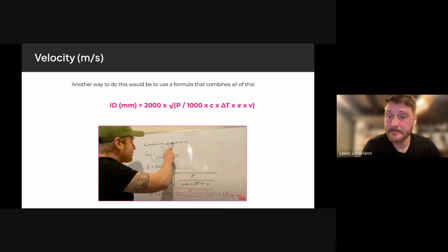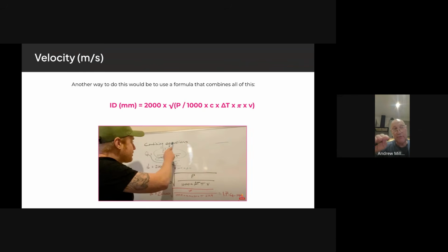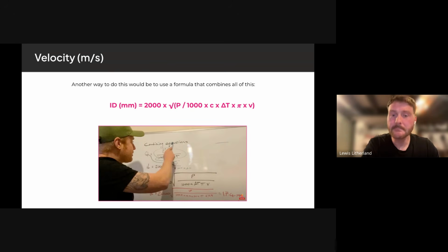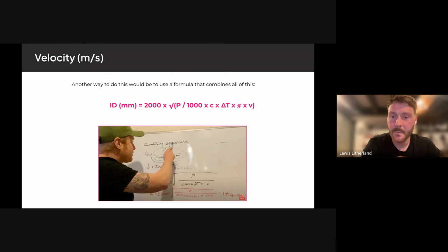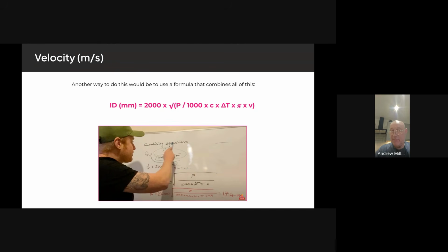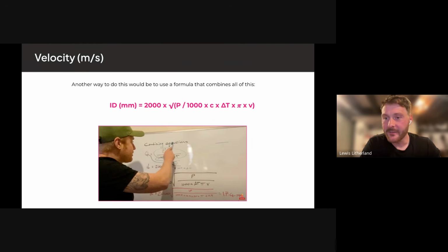I use this formula all the time. I don't do the process you've taught. I just look up the power needed for a circuit, put it through that formula, look at the diameter it gives me, and if my pipe's near enough, it's near enough. So it's a really quick, easy way of doing it. But I've always got it in the brackets in that second section, and you'll get the wrong answer if you don't have the brackets there, I think, but maybe you'd like to check. Brilliant, I will double check that. Thanks, Andrew. No problem. Thank you, I appreciate it.